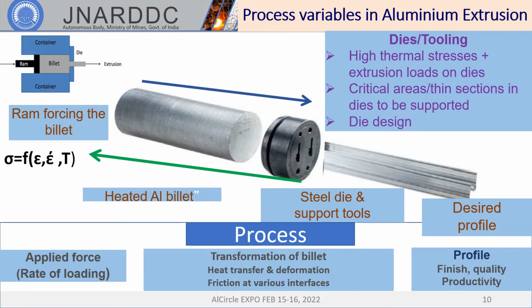Also, the dies and tooling need to sustain high thermal stresses and extrusion loads. Critical areas or thin sections in the dies need to be controlled or supported. Die design controls the metal flow.